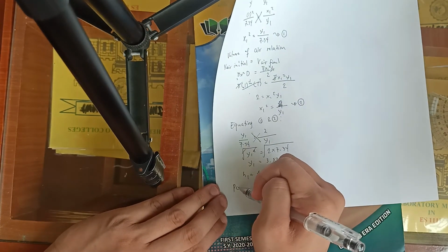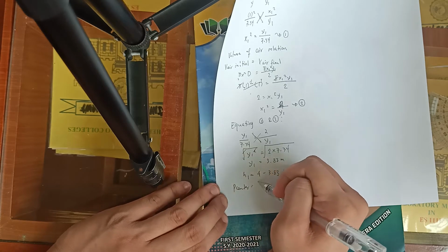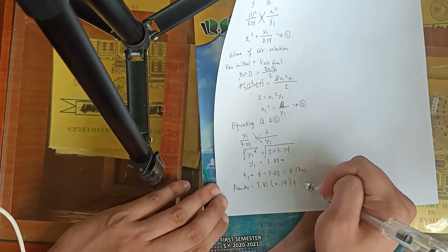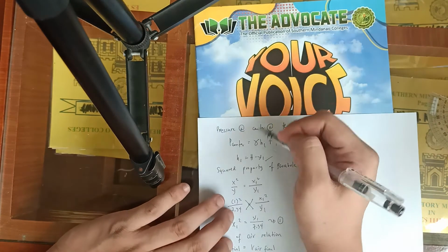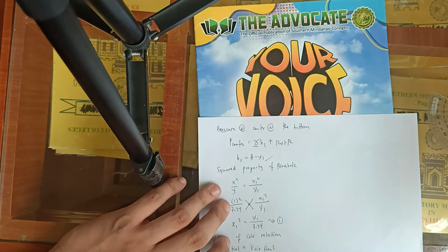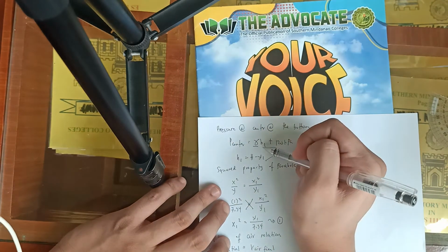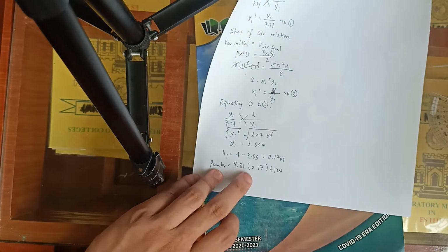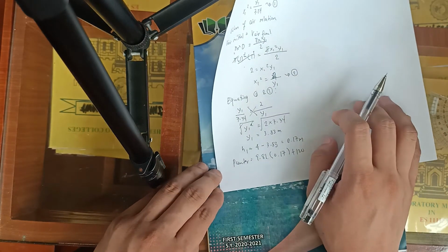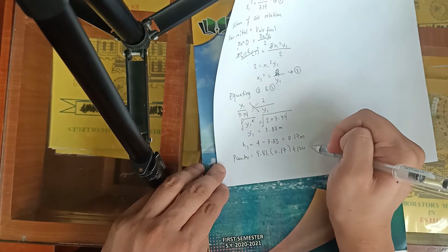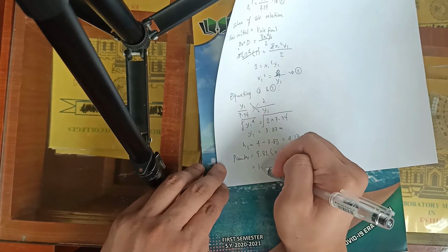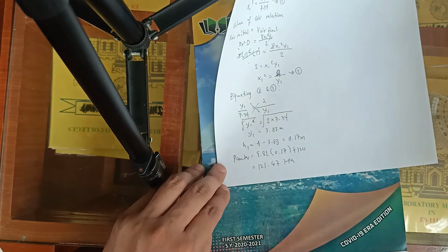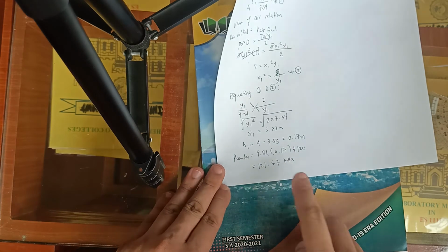So therefore, the P center equals 9.81 times 0.17 plus 120. Unit weight, since this is water, so specific weight is 1. And the h sub 1, no? So, 9.81 times 0.17. So, the answer is 121.67 kilopascal. I mean, one way to get the answer,